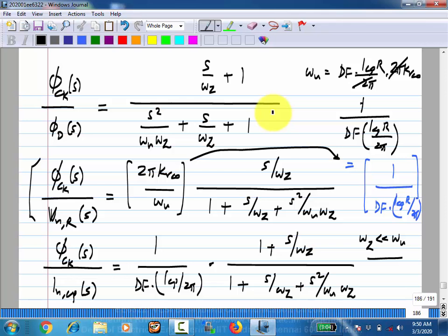But when you have a single line, and especially one which spans a longer distance, then it is a significant overhead to use another link just for the clock, because if you do have another link, you may put it to use for data, right? That's a lot more productive. So then you try to recover the clock from the data. Okay. So please plot these things, and we'll continue the discussion.